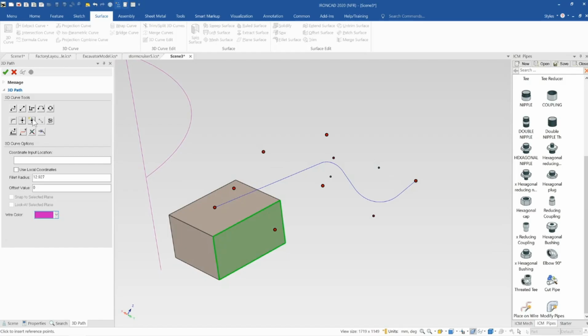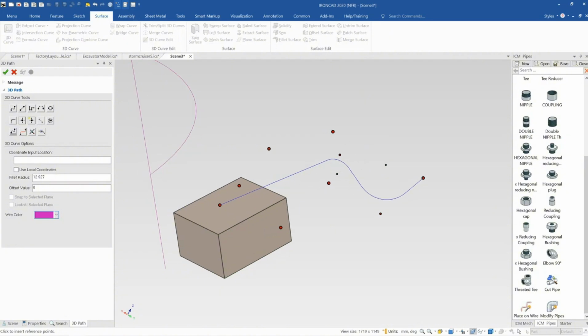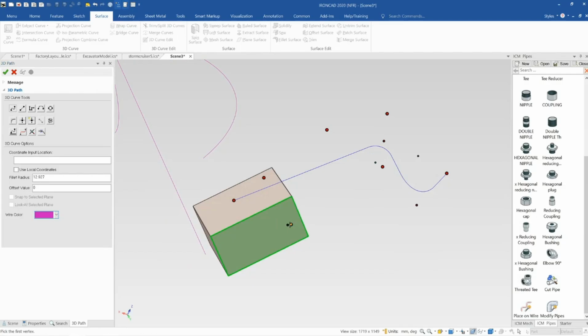So we have this option checked here, which is going to show them in the 3D scene when we finish the command. So you can see if I now select a spline, I can actually use these as snap points. For example, I may want to go in earlier and add all these points with the tri-ball just to get my points where I want to snap the 3D curve to, and I could go in afterwards and say, okay, I want to snap between all those points I just made with my 3D curve. Just like that.